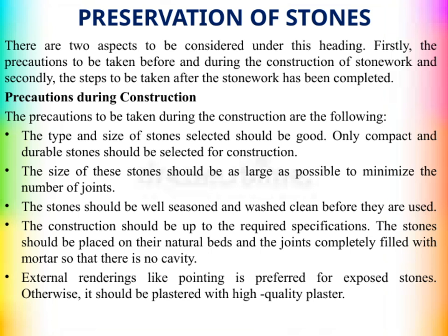Next, the size of these stones should be as large as possible. Larger stones mean fewer joints, which in turn makes the structure stronger and more stable. Also, it's important that the stones are well seasoned and washed clean before they are used. This helps in preventing issues like cracks or deterioration over time.